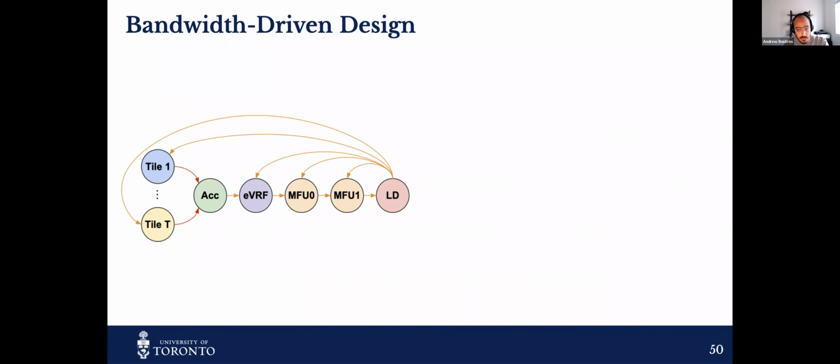So there's just a graph representation of the different NPU modules and how they communicate with each other. And then we start annotating those graph edges with the bandwidth of interfaces going between those modules in the baseline NPU. And you can actually see that some of the buses are really wide, so up to like 7K bits between some modules, and the smaller buses are even terribly wide.